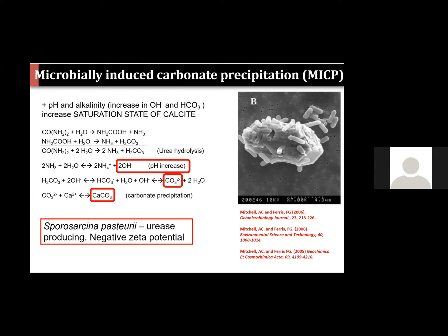We feed it urea. The hydrolysis of urea, catalyzed by the urease enzyme, produces carbonate and hydroxide ions. That ramps up the pH. You've then got free carbonate in solution, which can then precipitate with any free calcium in solution, thus forming the carbonate mineral. So that's really the principles of what this particular process is. And as I said, it's a nice simple process, which is why in a way it's been studied so widely as a way of manipulating biologically induced mineralization for various engineering purposes.